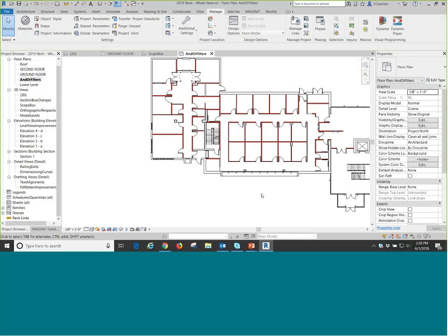We can filter out that way. So I was trying to think of a better example of showing this. It seems like with view filters, this is a very common way of doing fire ratings, so it's something that people are familiar with. So if we wanted to add some different conditionals to that, the ability is there to create those conditional statements, and I'm sure once we run into some different things in Revit where we're trying to get stuff to display a certain way, you'll figure out different uses of the and/or conditionals in the subset of the filter.